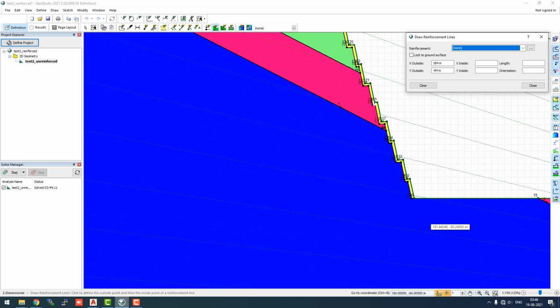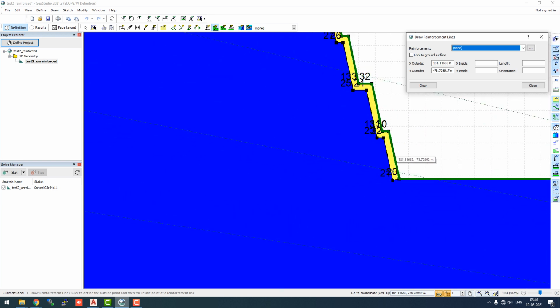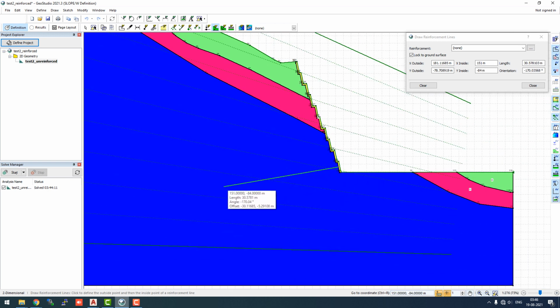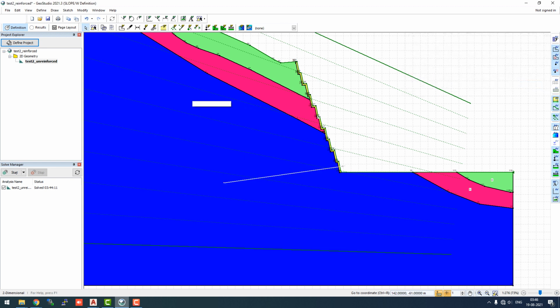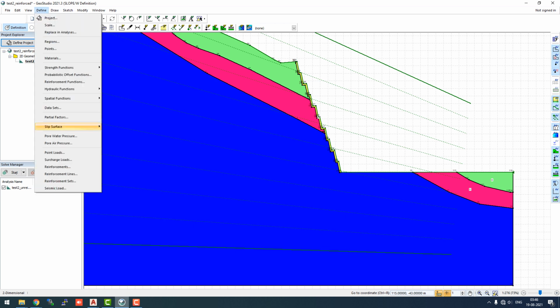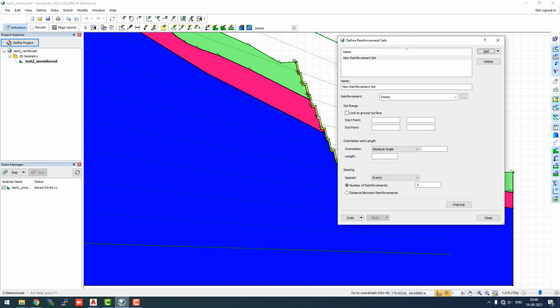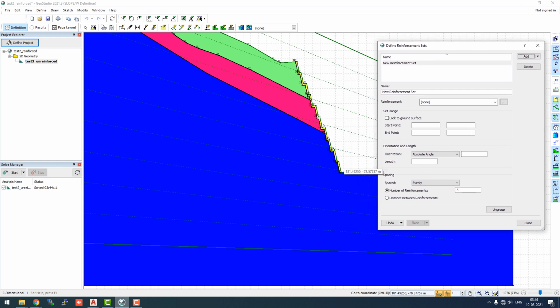We'll start from the bottom about the center of this RCC cladding wall, because we have seen in the diagram that our reinforcement should go like this. Sorry, I'm just going to close it right now, and undo this, and we have to define a reinforcement set first. We're going to click on add, and we'll add a reinforcement.